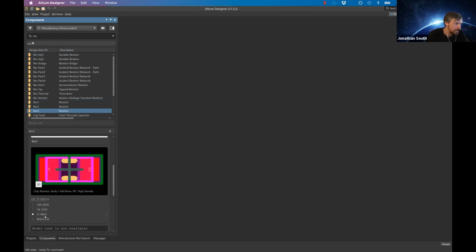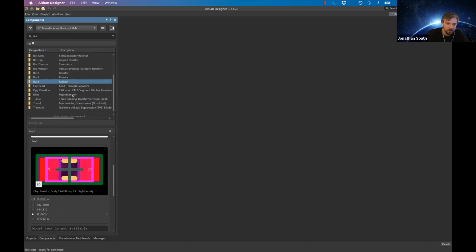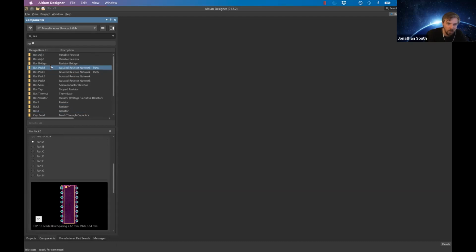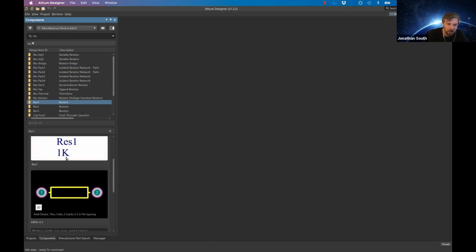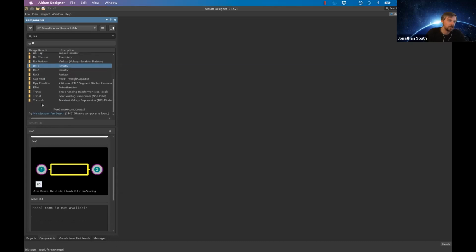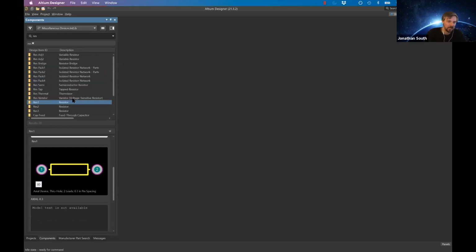Seeing some of those familiar designators like an 0603. We've got a few different options here. So it's basically looking for what combination of schematic symbol and footprint suits our needs. Now, obviously these can be altered after the fact, but typically to minimize headaches, you just try and look for one that's got all the stuff that you need. You can obviously make your own circuit schematic symbol, make your own footprint, make your own 3D model, and you've got yourself a component. But yeah, we've got those.